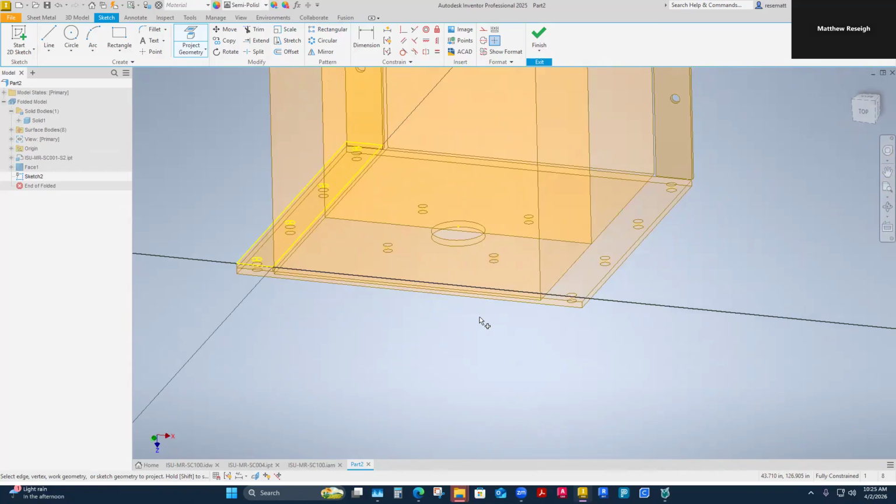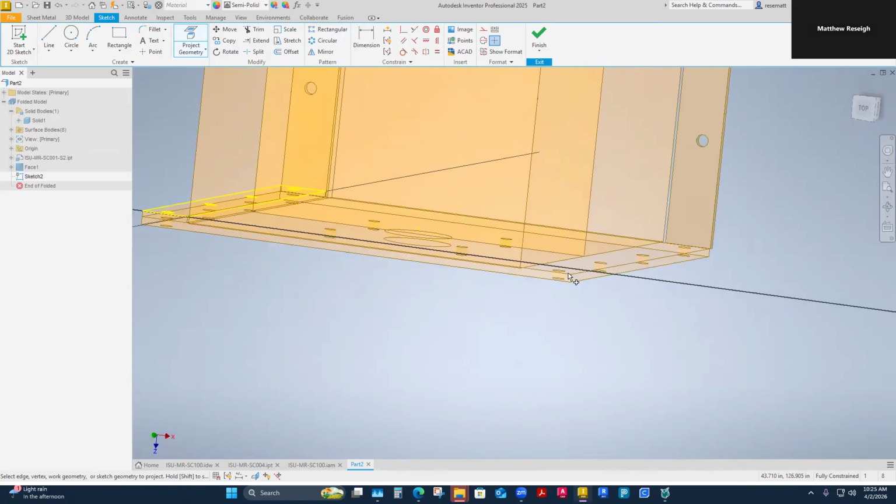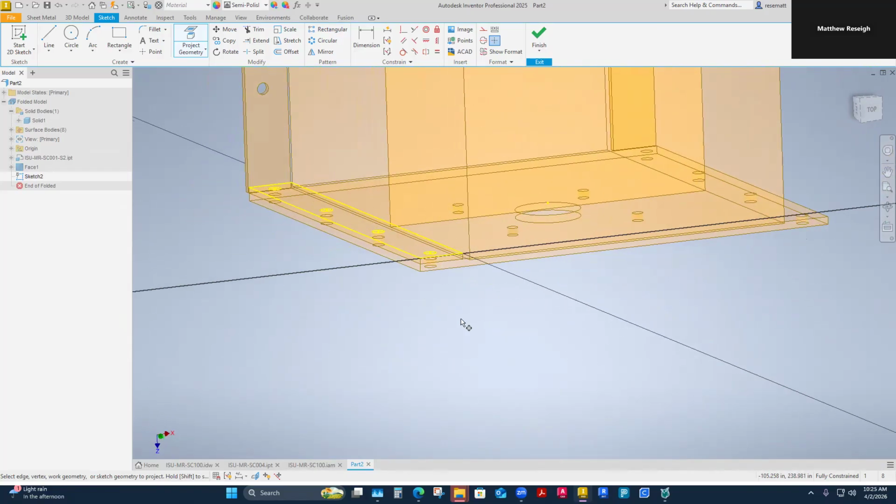You would have maybe been tempted to draw it over here as well, because it's the mating flange to bolt the end plate on. The end plate is removable, and I discussed that early on. That's so the auger can come out of the ends. I could pull this auger out of either side because both of my end plates are removable. That gives you access for maintenance, or it's not even just maintenance. It's also an assembly thing, because the way people maintain stuff is the same way people have to assemble it when they're actually building the parts.